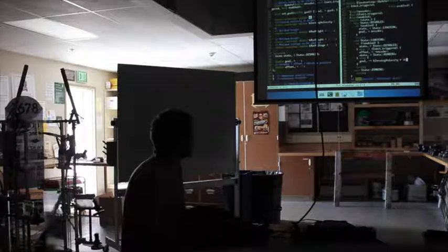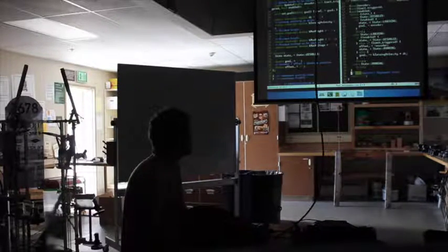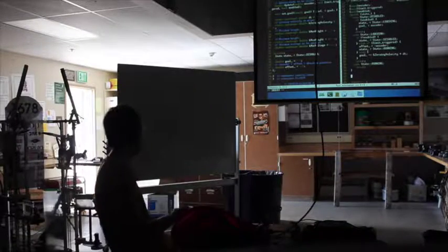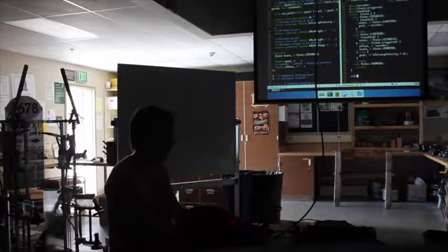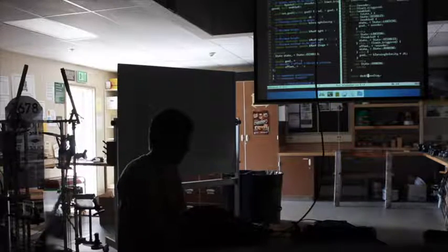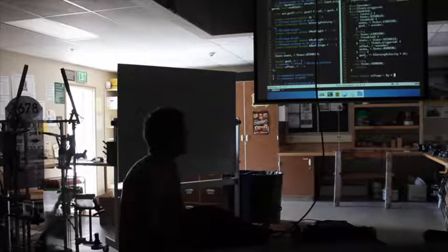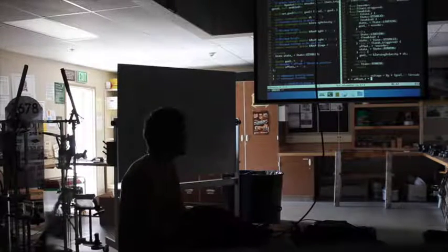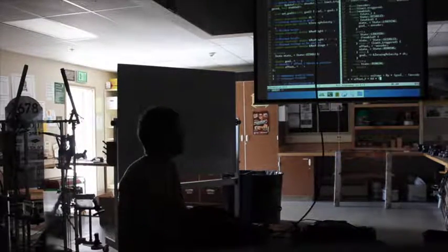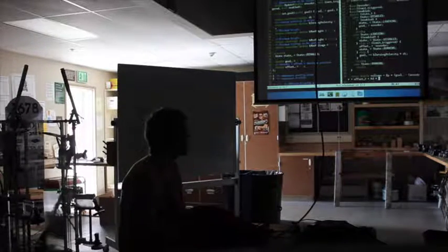Okay. So now we have something that's going to move through the states, and we need to implement it. So we want to implement a little PID loop here. The basic idea is some proportional constant times our error. So now we need to compute a derivative. We should probably save an error and a last error.